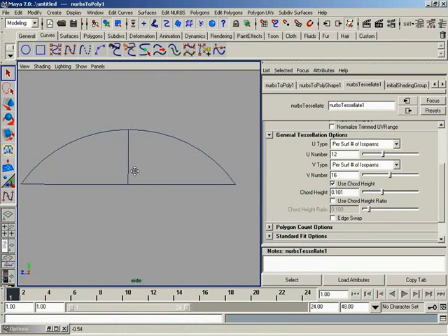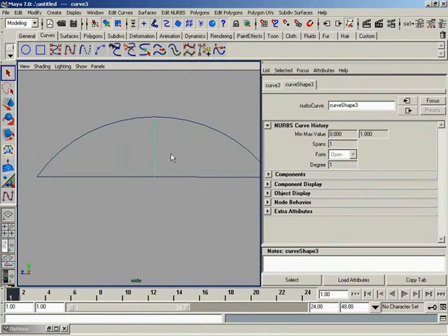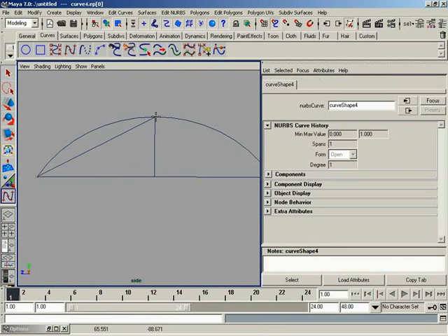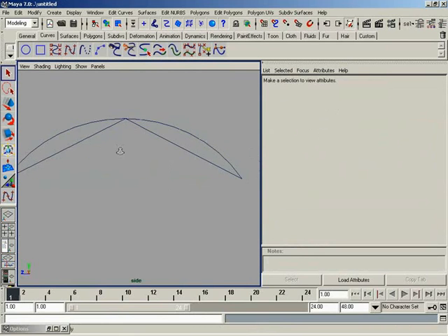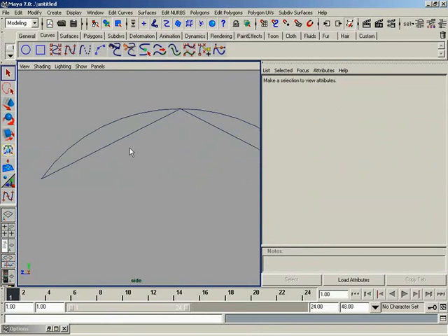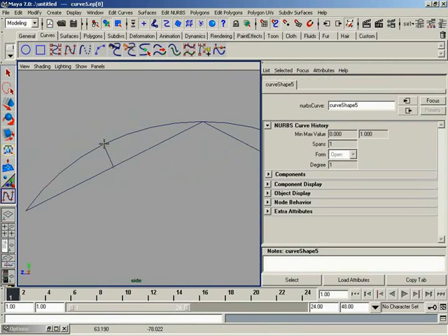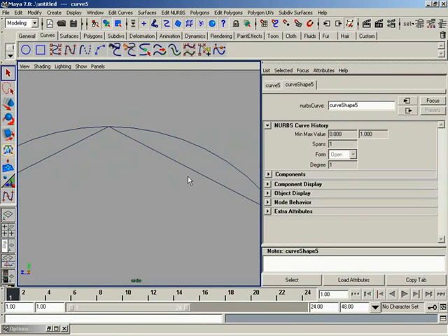Well, let's just come back over here. Let's say, for example, that this chord height was longer than the chord height that we specified over inside of our settings. Then what would happen is Maya would retessellate. It would create new polygon edges, like so. So we wouldn't be using this surface anymore. This is no longer apparent. We now have two sections instead of just one, and now we have two new chord heights. We have one chord height here, and another chord height here. And so it'll check both of these.